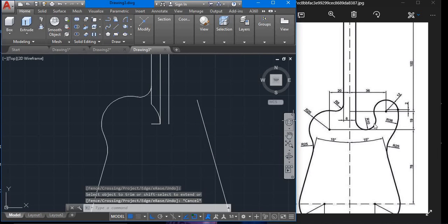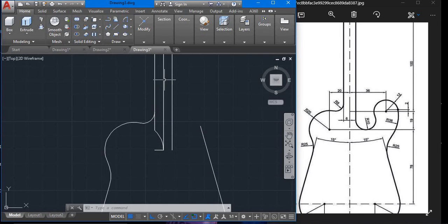And the next one we are going to be drawing is this particular circle, and from here we know that the midpoint of that circle starts from the end of the first line. So this is the first line, and this is the end point of the first line. So we are going to take L for line, we track it.